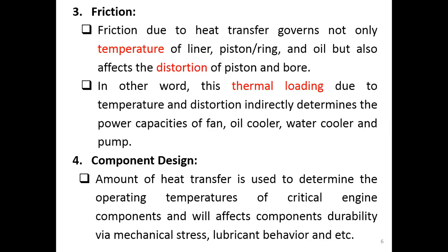Because if the piston has high temperatures, it can be deformed, and this deformation we call distortion. And when distortion happens, sound and vibration come out because the clearance is changed. So friction controls this.